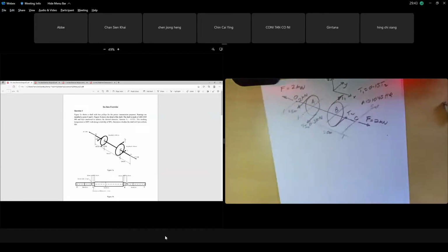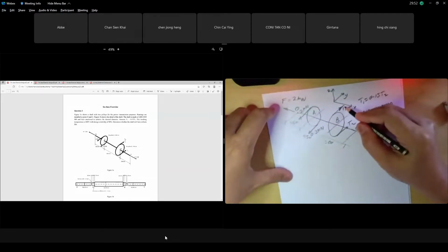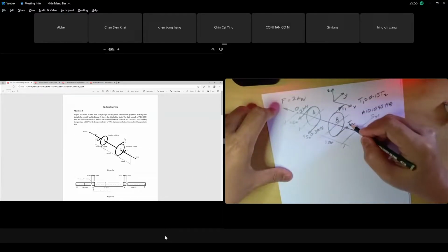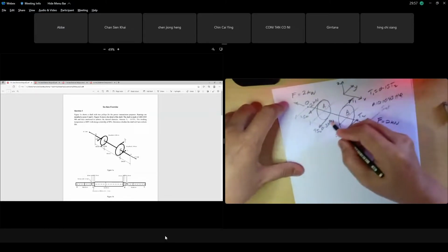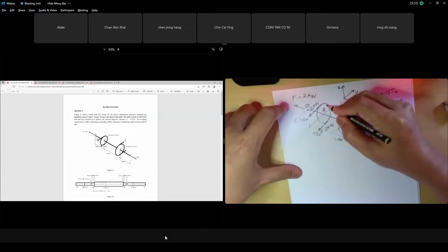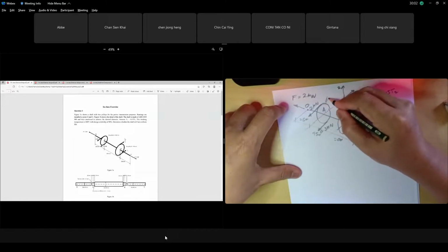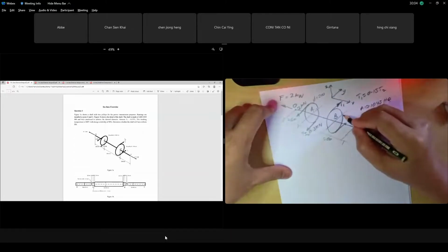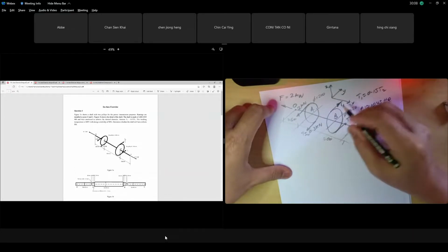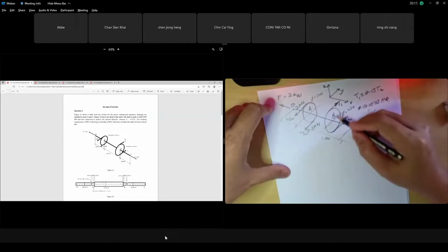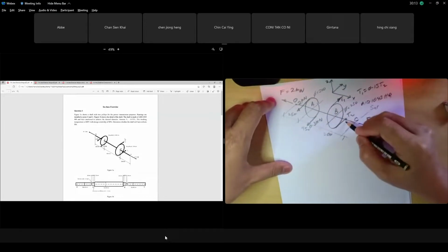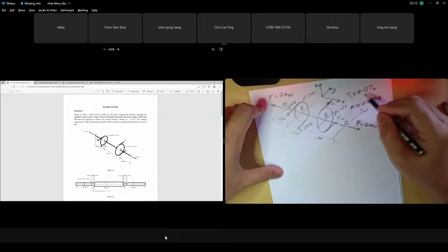We make the shear diagram and moment diagram. Can we solve for T1 and T2? Of course you can. This one is 0.2 kilonewton, 0.3 kilonewton. The diameter of the pulley at A is 200 millimeter, and the diameter at pulley B is 250. Remember, torque is force times radius, so times 100 for this one and times 125 for this one. To get T1 and T2, we know T1 is 0.15 T2.